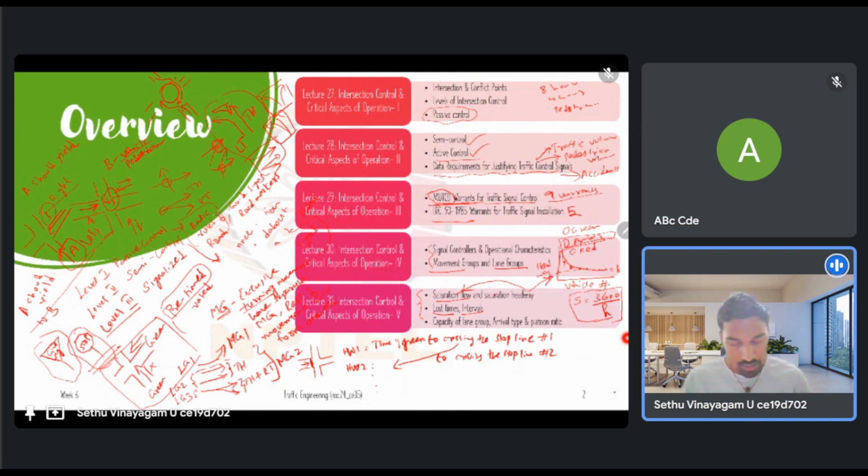Okay. So because the vehicles slow down, right? So the flow will be lesser than the saturation flow rate in that amber period. Okay. So that also leads to some time that is lost. So that is the clearance loss time, and the sum of these two, startup and the clearance loss time, is called the total loss time, right?